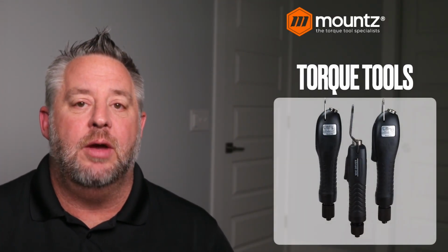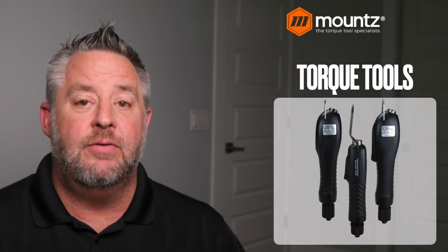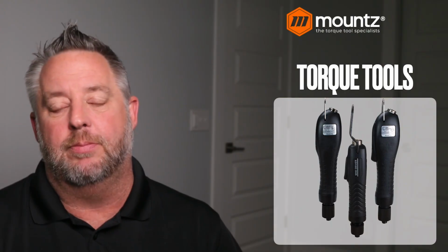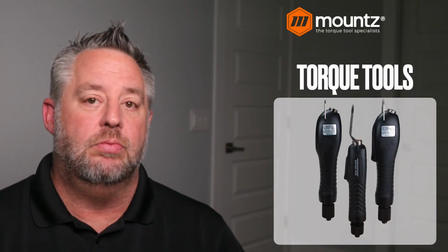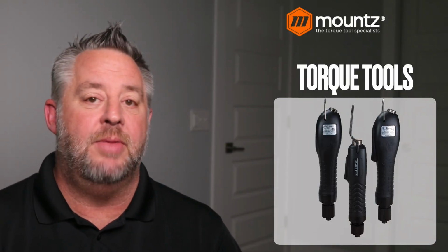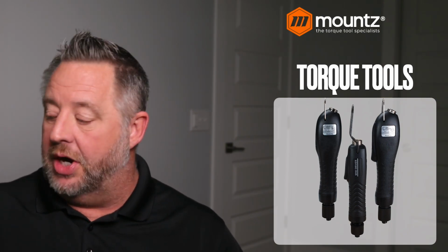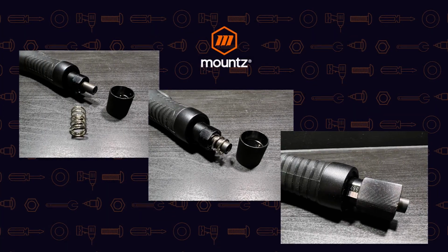Next, if we move into electric style tools, there are several different styles of these. There are brush motors, there are brushless motors, there are ones that have special features that will clutch out twice, some that have a special reverse feature in them. But these types of electric tools, again, are controlled by a spring mechanism or a spring clutch in them. And depending on how much we compress that spring to begin with, is going to give us our torque output.